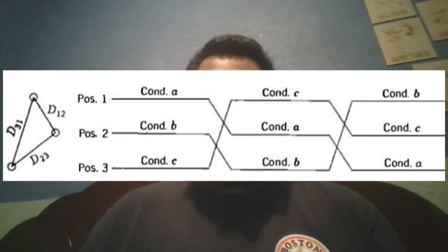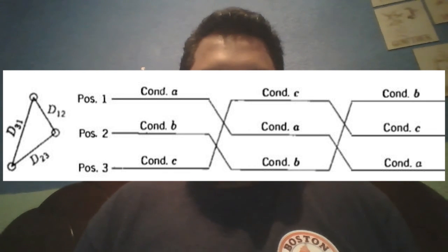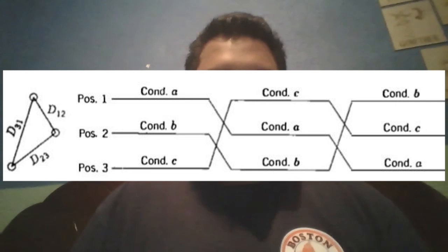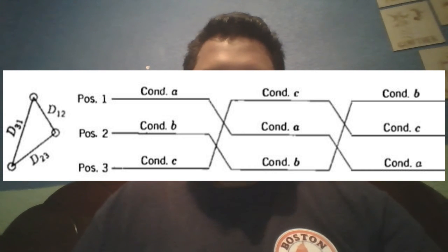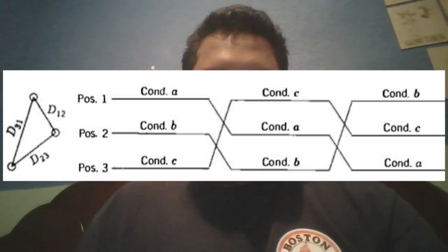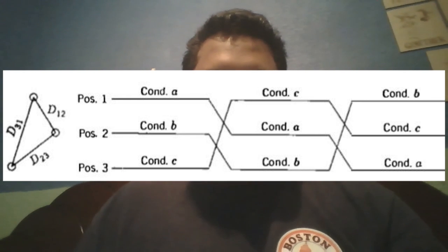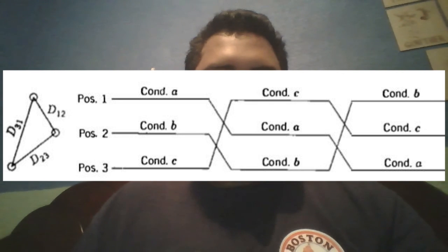Inductance of three-phase lines with unsymmetrical spacing. When the conductors of a three-phase line are not spaced equilaterally, the problem of finding the inductance becomes more difficult. Balance of the three phases can be restored by exchanging the positions of the conductors at regular intervals along the line so that each conductor occupies the original position of every other conductor over an equal distance. Such an exchange of conductor positions is called transposition. In the figure we can see the transposition cycle of these conductors.